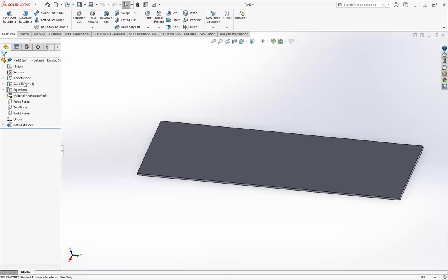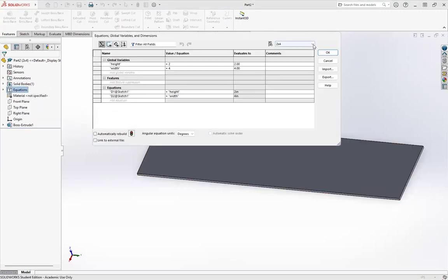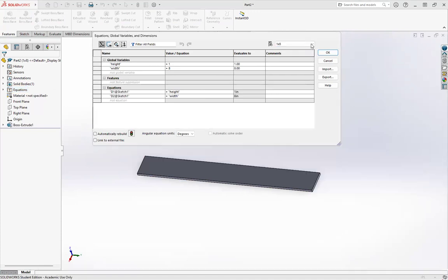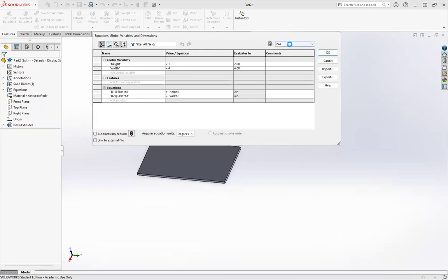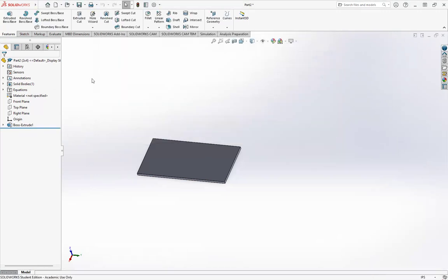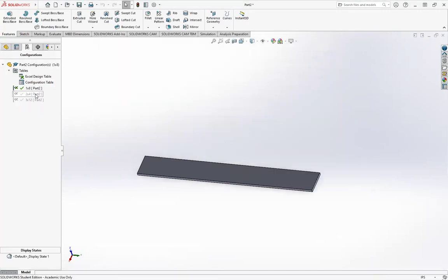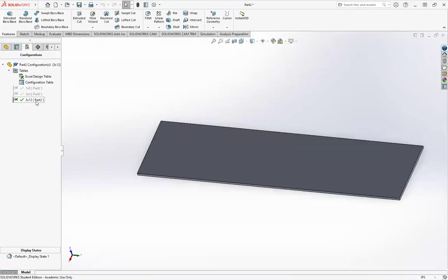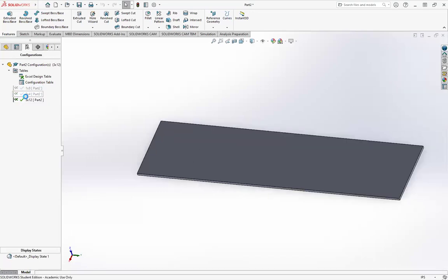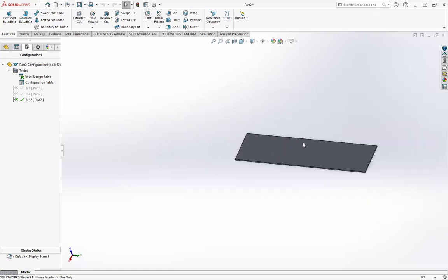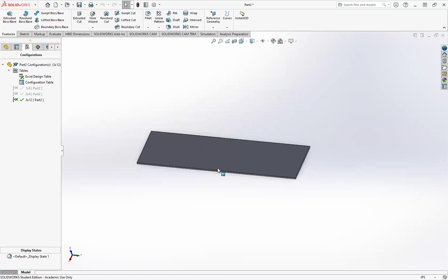And if I come over here and verify my equations, let's see, manage equations. So 2x4 is 2x4, 1x8 is 1x8, 3x12. Notice the values are changing. There we go. Now we're changing. We just needed to force an update. So a really quick video, but that gives you an idea of how these can be changed.